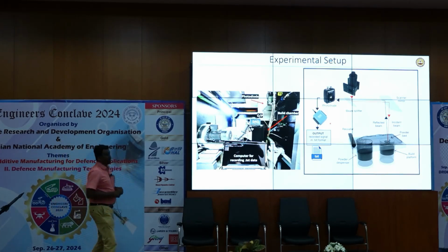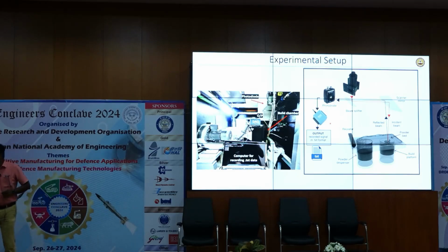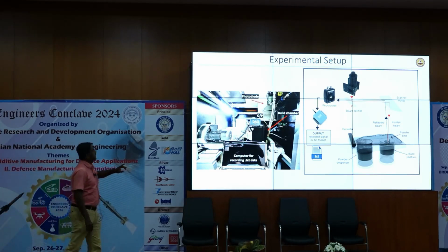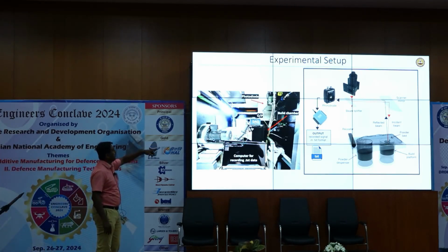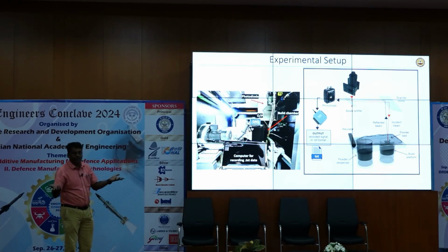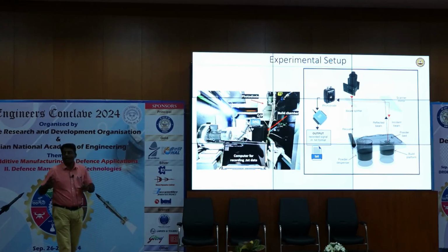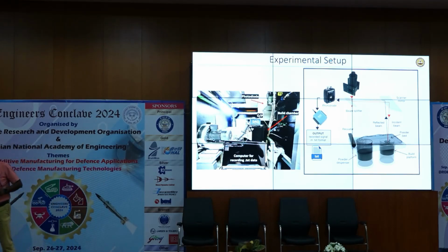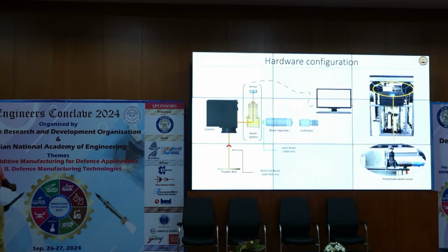Okay, so this is one of my students' MS thesis, what you see here, the actual ray diagram. Anyway, the idea is very simple. We use a simple photodiode which is monitoring the reflected laser beam. If it is stable, well good, we get the voltage signal. If it is unstable from a defect, then the voltage signals will tell us something else is happening other than simple melting. Let's skip the actual part of it.